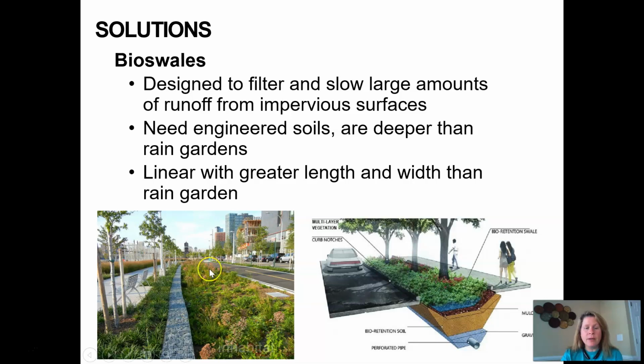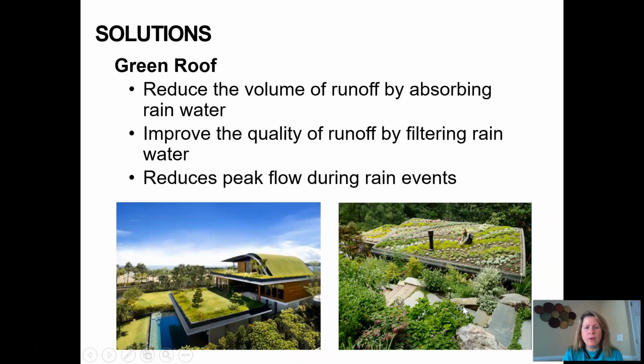Bioswales is another way to handle runoff. This shows you've got a bunch of rocks and some screen over it to keep it from moving. But as you get a lot of rain, it allows that water to seep in and flow without causing erosion here. And then here's another example of a bioswale where we have trees growing in. Green roofs, we talked about those before.